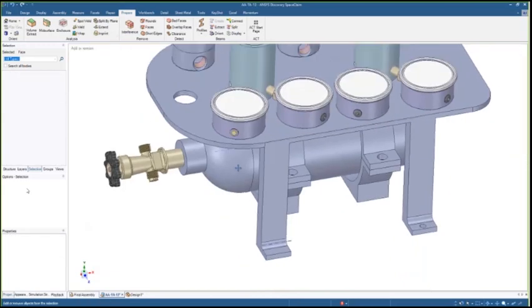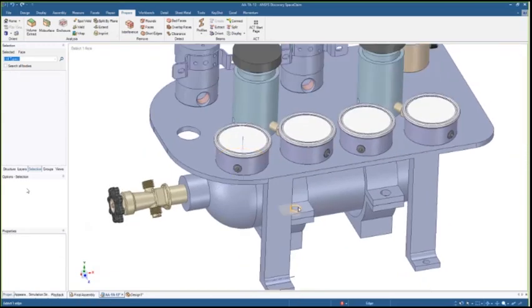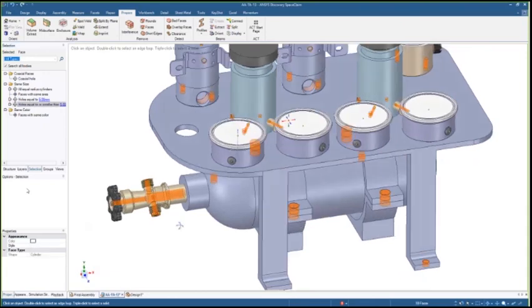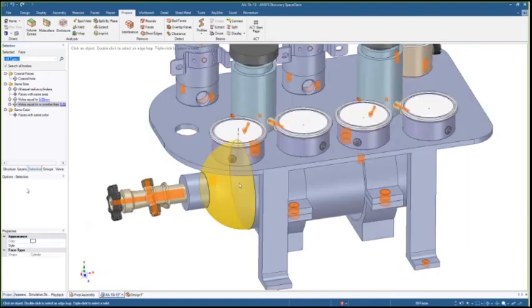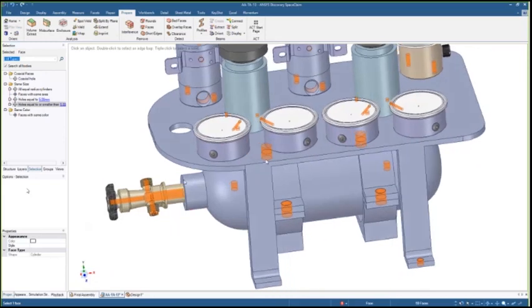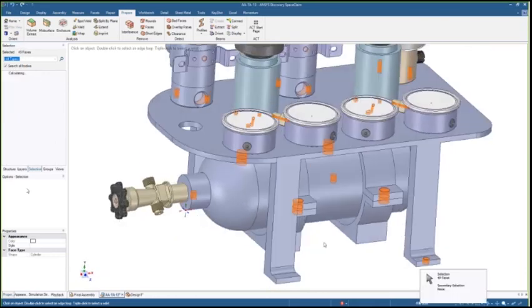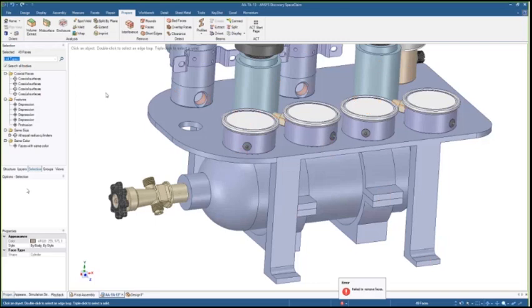But I can also search for holes. If I want to grab all the holes of a certain size, I can search all bodies and easily grab all holes equal to that size and smaller. Now, some of these holes I may want to remove, but other holes I may need. So this is just a starting point. If I hold Control and do another box select, it will deselect what's in that box. Now I've got 49 holes selected, and we'll hit F for fill, and it's going to go through and remove